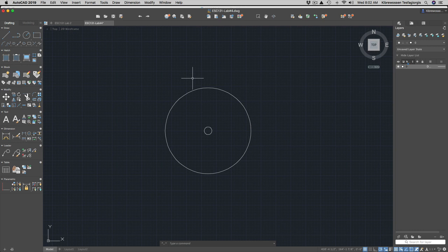If you just simply type 16 and press enter, it means 16 inches. AutoCAD will understand that as 16 inches. So for that reason, I pressed a little too soon. I'm going to do circle again. I'm going to find the center of that circle again. You know, when you hover the cursor around, then you'll find it's 16 feet.